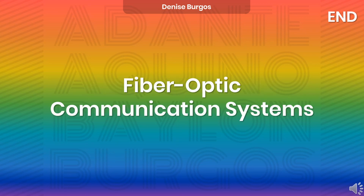The main components of fiber optic communication systems are the fiber optic cable, the light source, and the light detector. In the light source, there can be a source-to-fiber interface and an A/D converter. In the light detector, there can be a fiber-to-light-detector interface and a D/A converter. There is also an amplifier and shaper to take into account the attenuation and distortion that happen as the signal